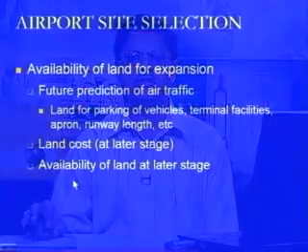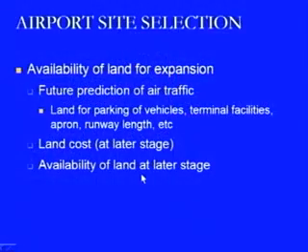Next is the availability of the land at a later stage, which is another factor, if it is not acquired initially, looking at the future expansion required. If it is not available, then we have to shift the whole airport, or we have to provide some additional space, and on that additional space the additional facilities have to be created. So, it is a more costly affair.